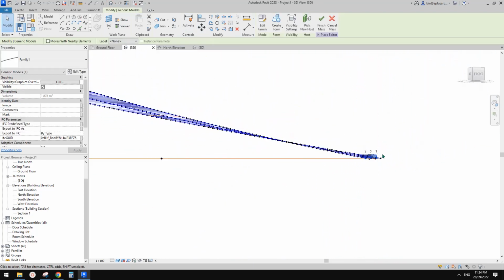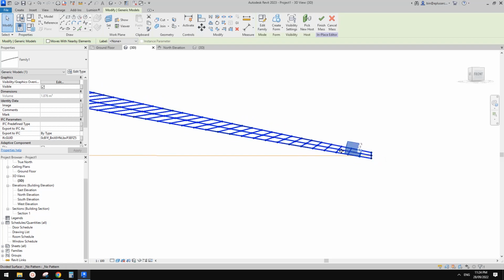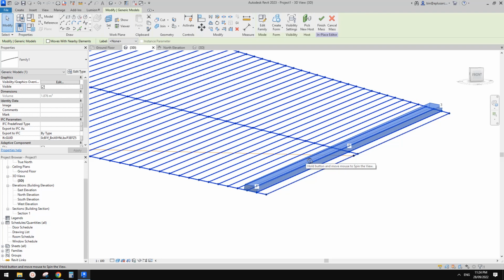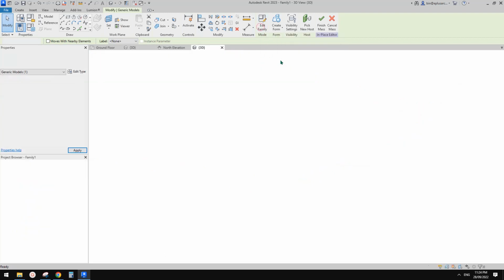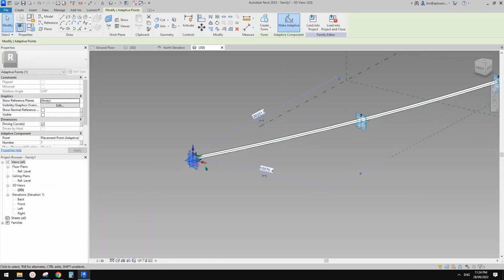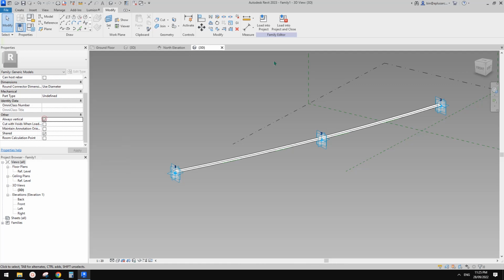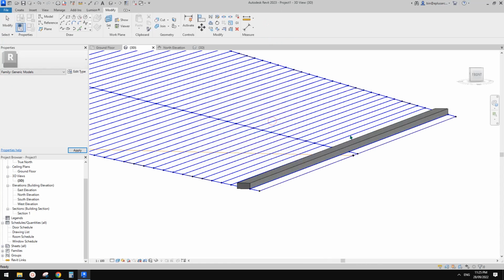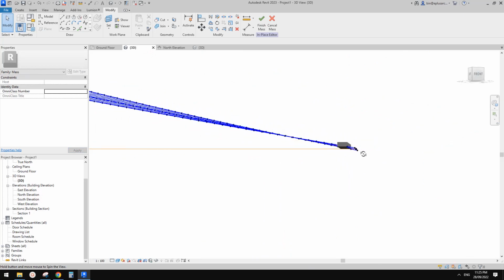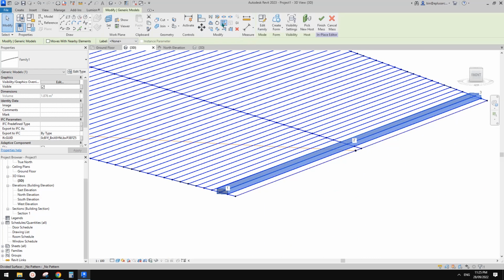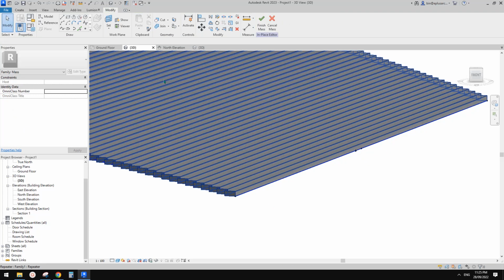I think this one looks like it's following the direction of the surface, so we don't want this. So maybe let's go back, and I am not sure. Let's try this one first, always vertical, and see what happens. Load back, override. Yeah, so this one works. So now select it, repeat, and this will create this adaptive family all the way up.